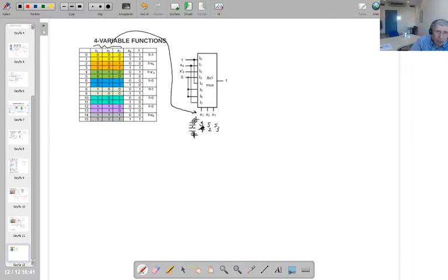So if you use the three select inputs, you're going to divide this function truth table into 8 groups. This blue one, that's the orange one, green one, blue one, light green one, dark green one, violet, and the black one here. These are 8 groups. For each group, I'm going to compare the x4 variable value and the function value, and write it here. So in here, it is independent from the x4 variable, so f equals 1, it goes like that.